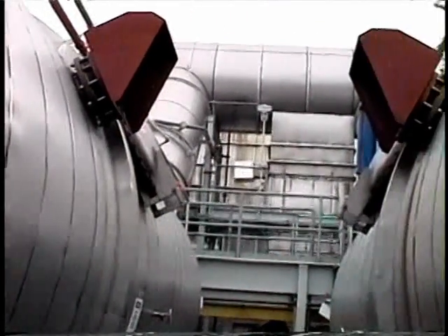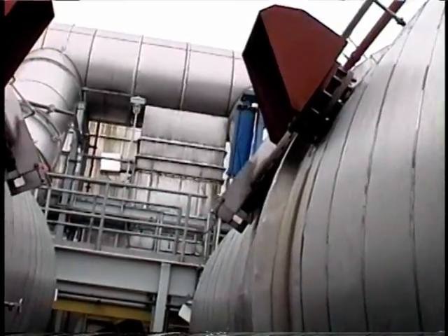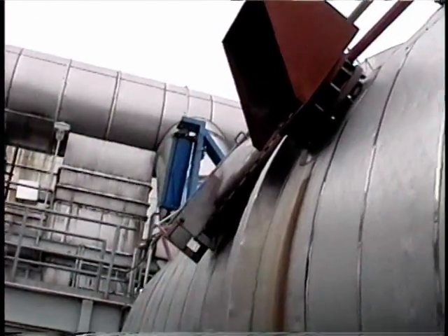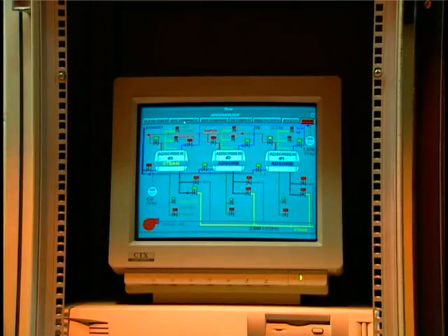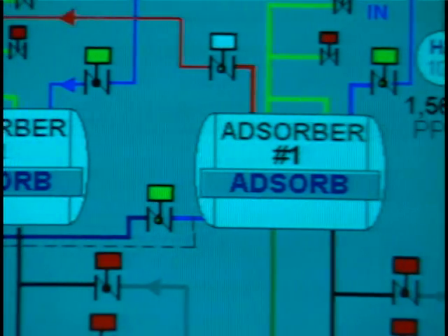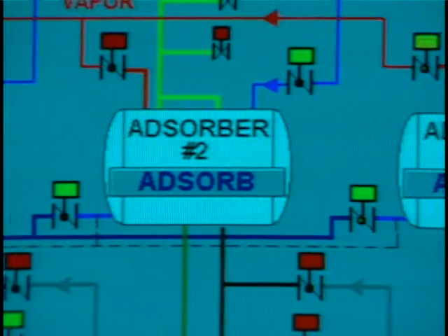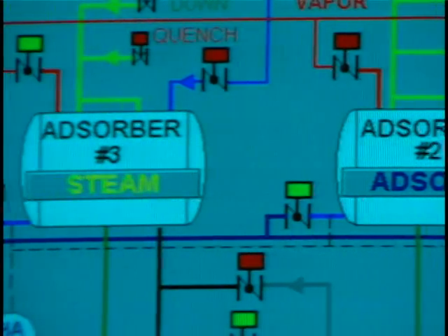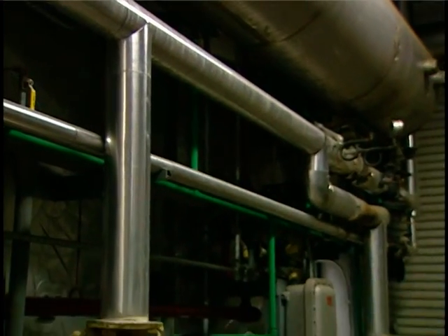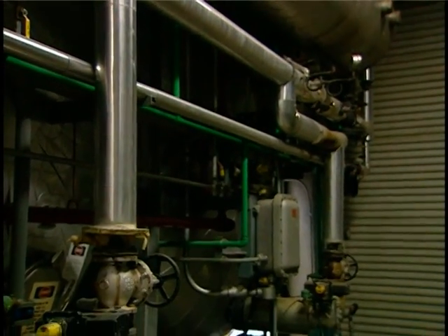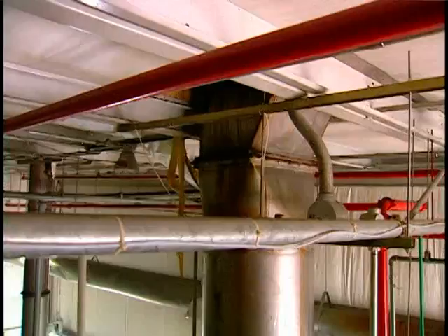If the adsorber is regenerated using steam, measurements should not be taken when the adsorber is in the purge cycle. The purge cycle begins after regeneration is completed and is used to dry the carbon bed and cool it down before it is put back online. During this period, water droplets and high humidity are present, and this moisture can damage the instrument sensor.